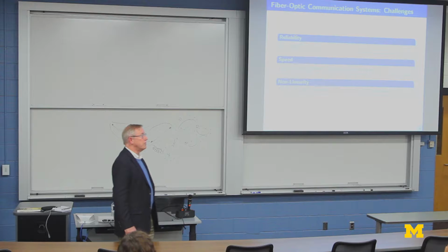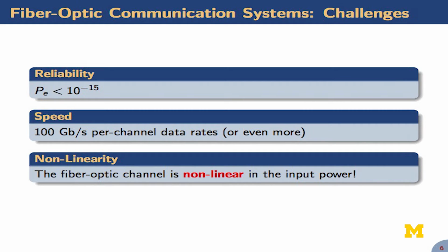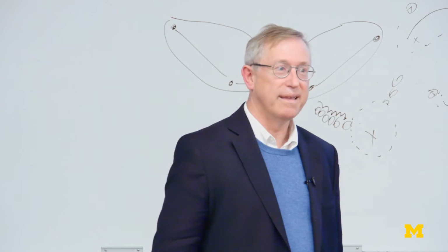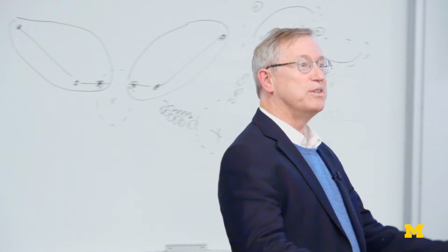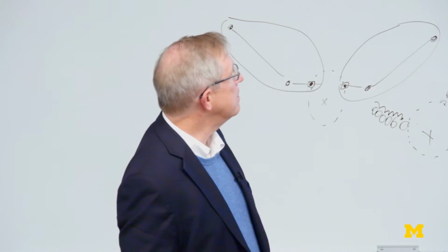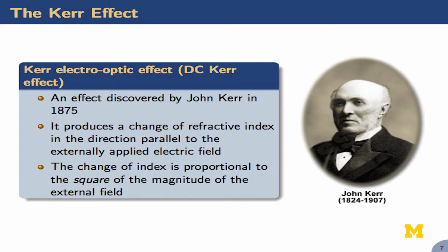What makes it interesting from an information-theoretic perspective, and that's really why I'm interested in this channel, is that the fiber optic channel is nonlinear. It's a nonlinear channel, which makes it extremely interesting, or let's say extremely challenging to try to work with from an information theory point of view. And this nonlinearity comes about from something called the Kerr Effect.